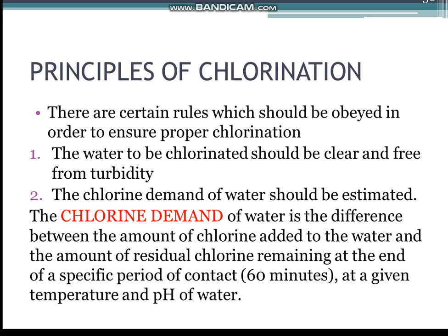Principles of chlorination. There are certain rules which should be obeyed in order to ensure proper chlorination. First of all, the water to be chlorinated should be clear and free from turbidity. Turbidity impedes efficient chlorination.